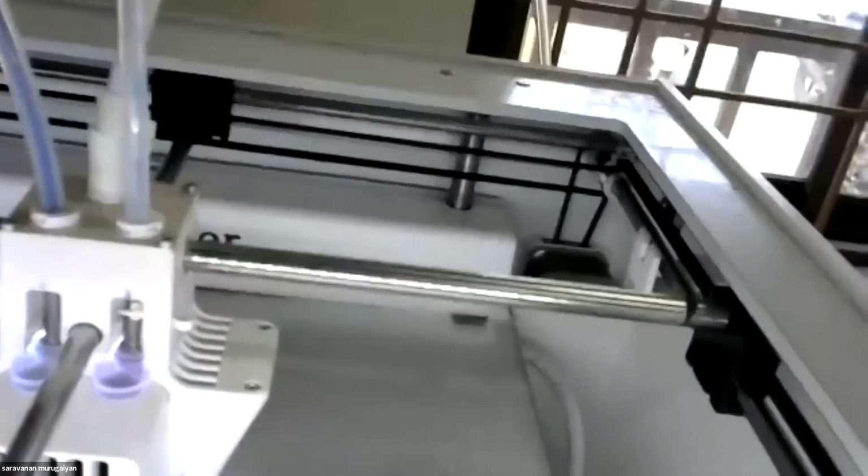the movement of the machine is controlled with the help of 3 different stepper motors. As you can see, 2 of them are at the top, and one is fixed below the machine, hidden inside. The base plate is made of glass and it consists of a heater as well. Since we need to maintain a uniform base plate temperature, which is necessary to reduce the residual stresses as well as for easy removal of the part, the base plate is uniformly maintained at a temperature of 60 degrees centigrade for this blue polylactic acid material.